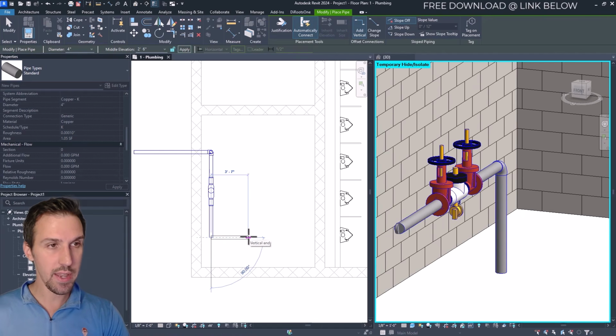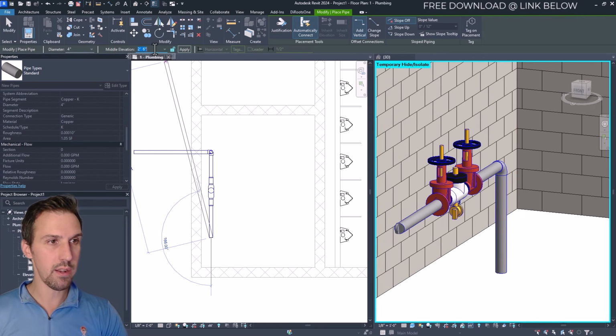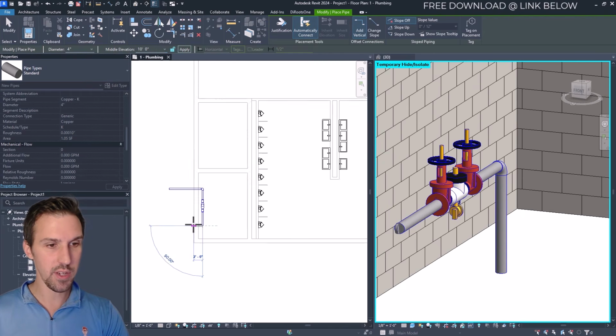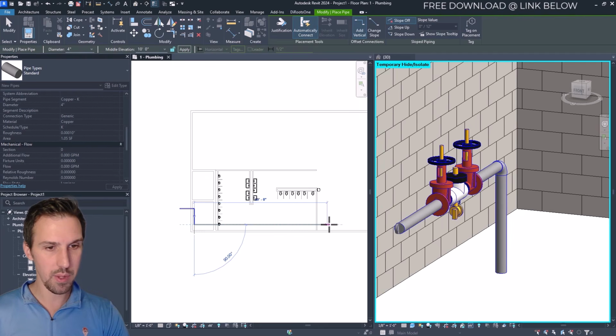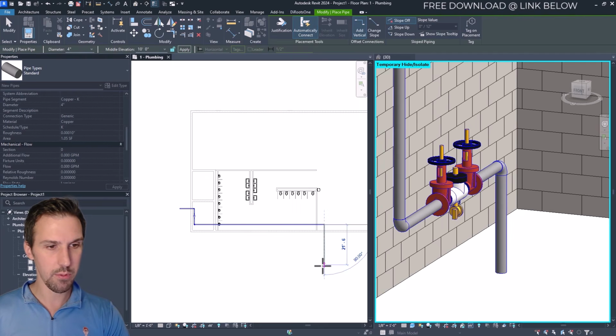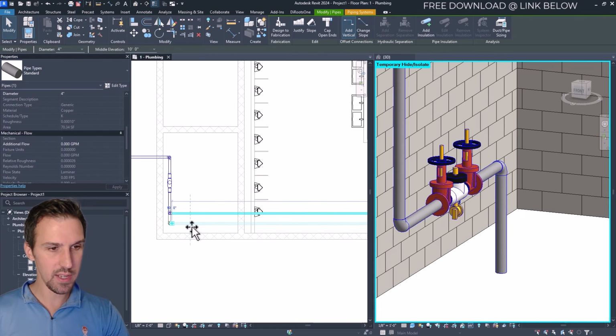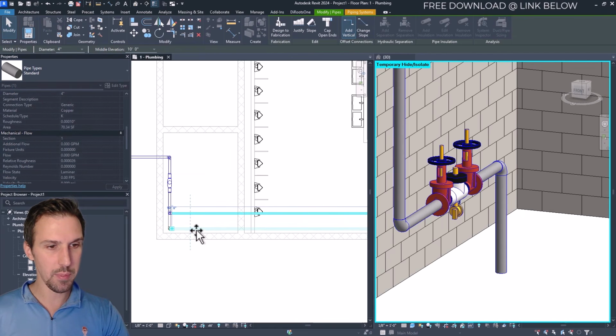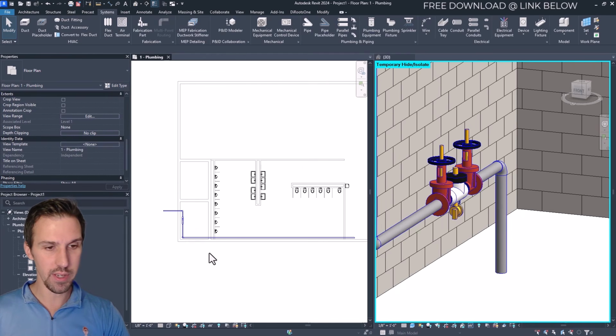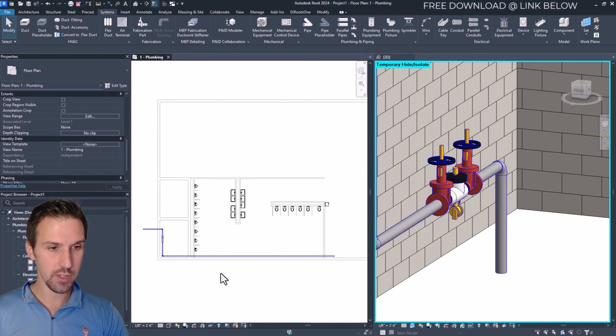That looks good. And now this time I want to raise my piping up. So let's raise it up to, I don't know, 10 feet. So we're going to click on, type in 10 up here on middle elevation, and then we're just going to start drawing our piping off to this direction into our fictitious building. And I'm going to go ahead and move this down, so you can literally just drag your piping to move it, which is really nice about Revit. And this is looking great.